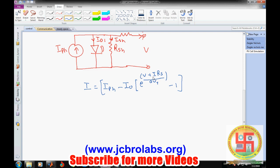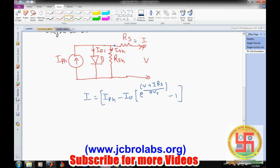The voltage applied across the diode is V plus I times RS, because we are going back side. And then finally, minus (V plus I times RS) divided by RSH. This is the ISH current, the voltage here divided by resistance, and this is the diode current. So it is pretty simple: IPH minus all the currents, and we will get the value of I.